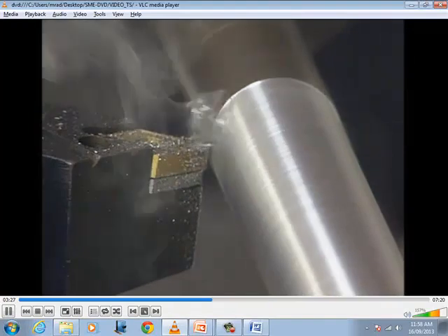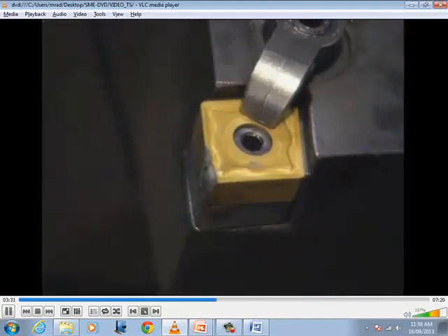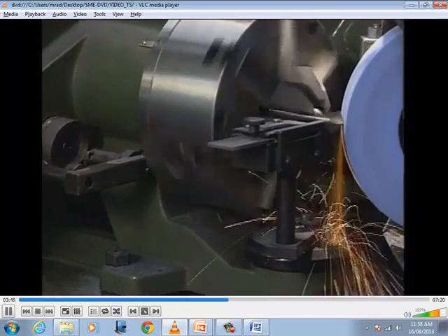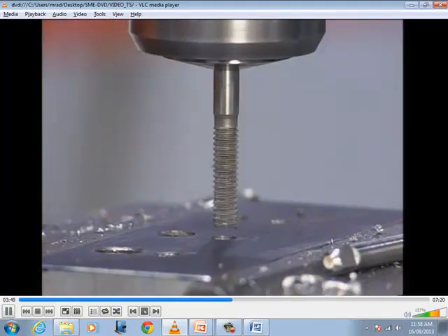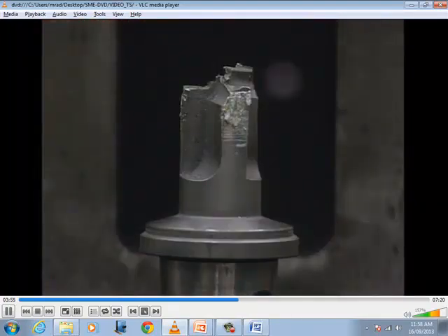All cutting tools have a working life, and then they dull, fail, or fracture. For this reason, they are called perishable tools. The cutting tool life cycle may be a single use or involve indexing to multiple edges, as with an insert, or multiple resharpening, such as with drills, end mills, and taps. It is a safety hazard to run any cutting tool until it breaks. This creates scrap, impacts tool and part costs, and reduces productivity.